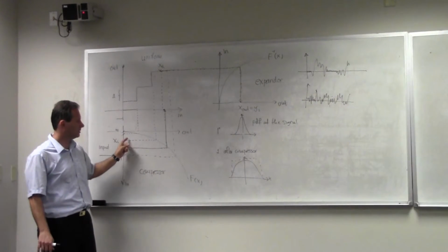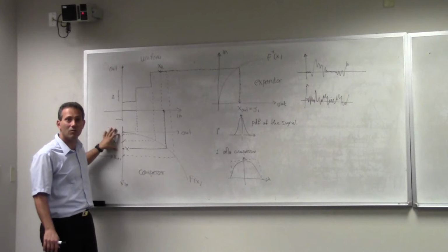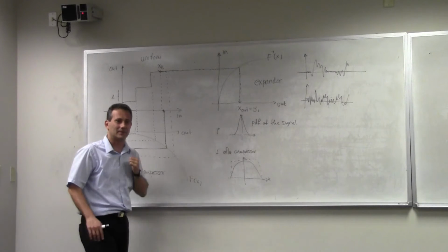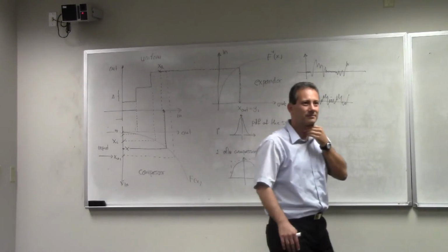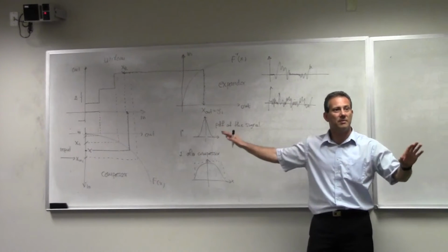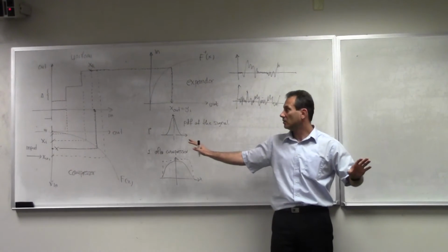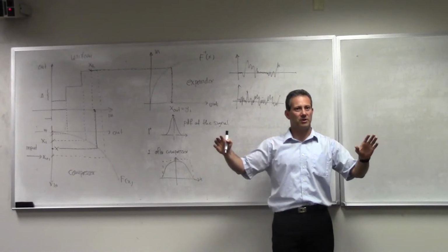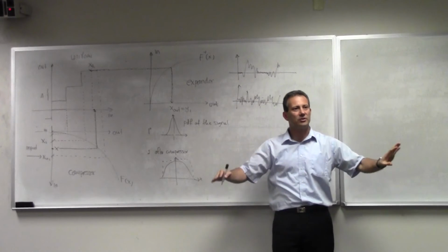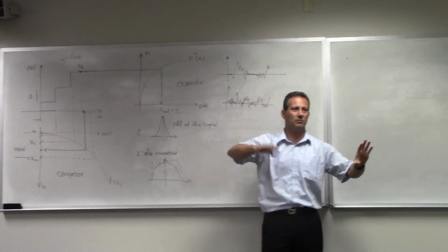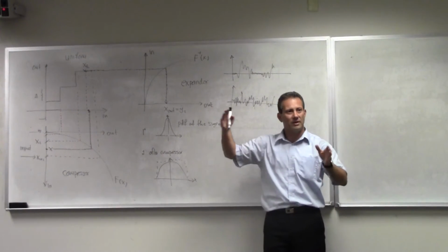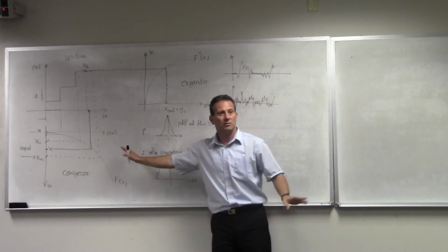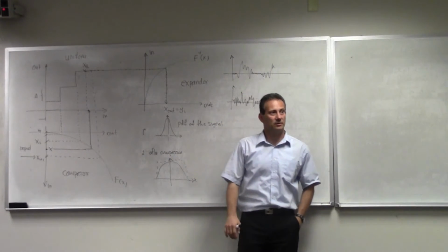It does that by expanding on the low end and compressing on the high end, so it's always in the middle. When you say low, we're not talking frequency, we're talking purely magnitude, voltage. Remember I talked about our view of random processes, magnitude domain and time domain. We're not touching the time domain right now. We're living in magnitude, looking at the random variable that is the amplitude of your signal. This has nothing to do with any frequency content of your signal at all.